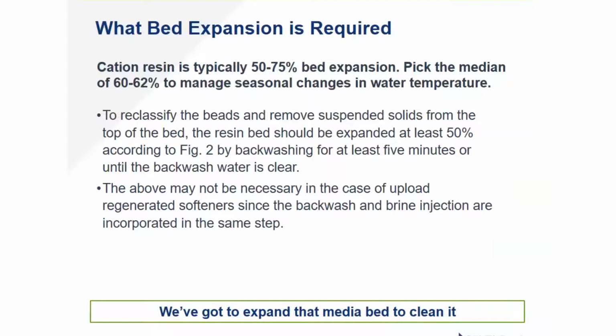The above may not be necessary in the case of an upflow regenerated softener, since backwash and brine injection are incorporated in the same step in some processes. I do encourage that you use a backwash even in your upflow just after the brining. We want to get that bed clean. So we've got to expand the media bed in order to clean it.